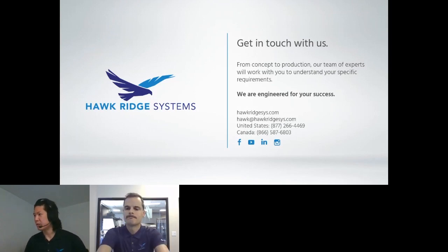And there's a question here about why adding additional variables, I presume referring to the dynamic approaches for static problems, helps. And in the question statement here, maybe iterations are no longer required. If you're still using an implicit solution, you do still need that equation to balance even with the additional terms. But the additional terms help because they give us additional terms to use to balance the equation. So dynamic approaches naturally tend to balance a little more easily than the purely static approach.